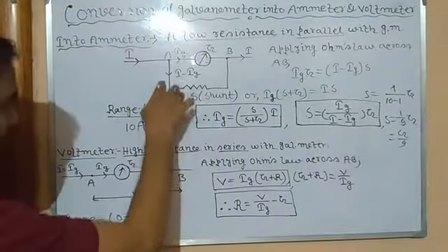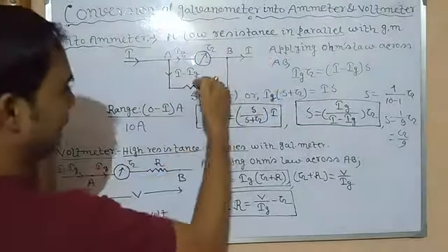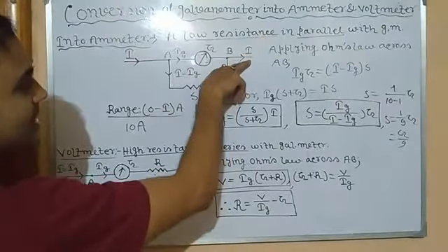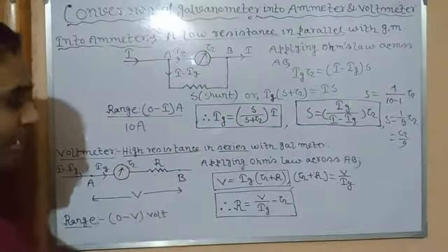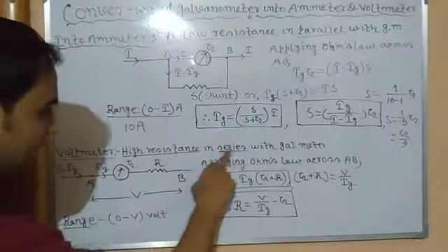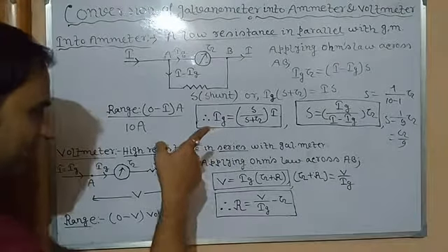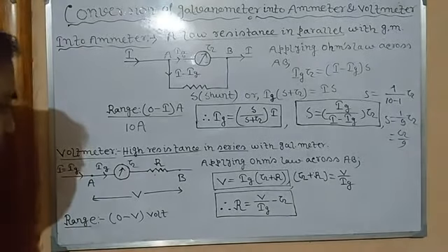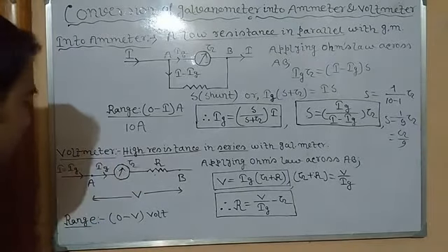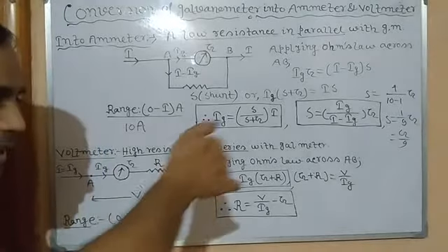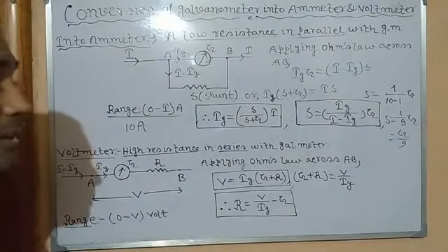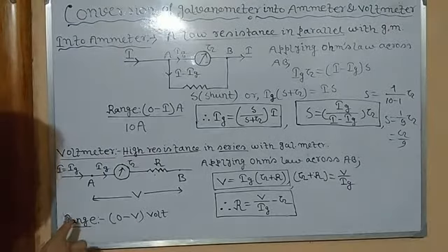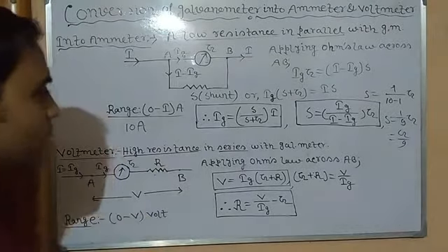With low resistance, current can easily pass through the bypass. In parallel, if it were connected in series, it would increase the resistance, and then current could not pass through the ammeter. Here with high resistance, current cannot pass. In series, resistance will also increase. If it were connected in parallel, the resistance would have been less. We all know that if a high resistance is connected in parallel, then reciprocally its resistance would be less. If it is less, current can easily pass through, which will violate the function of the voltmeter. So that's why it is connected in series with the galvanometer.